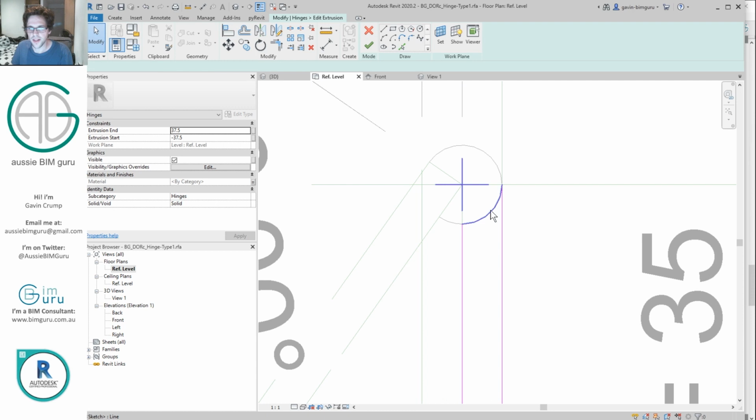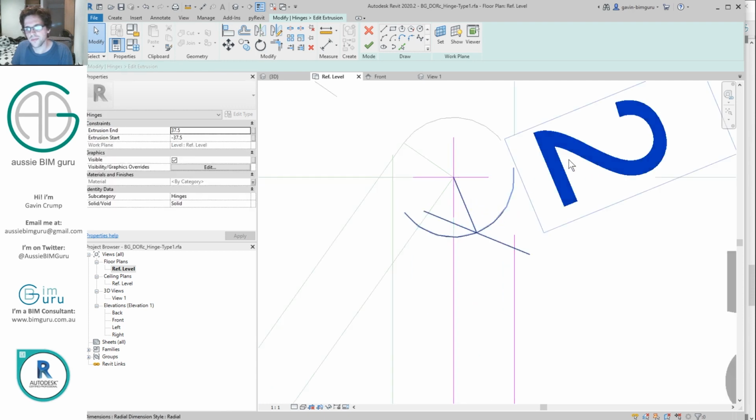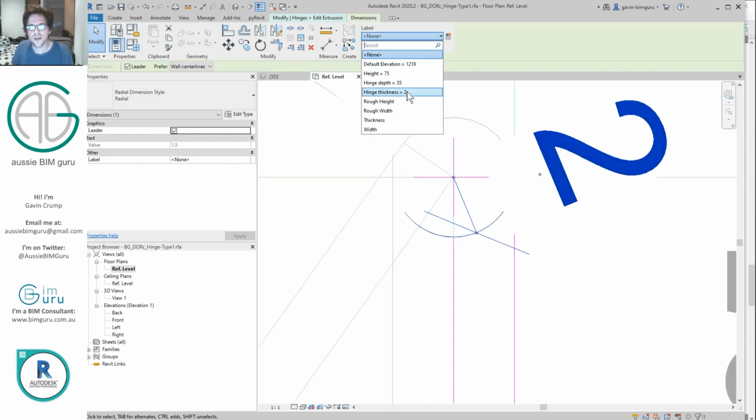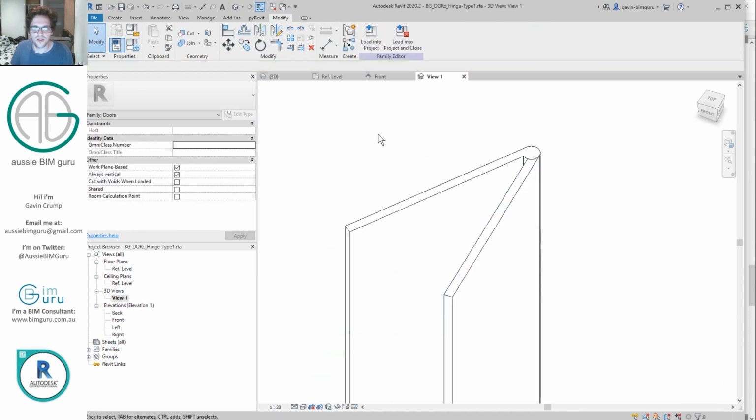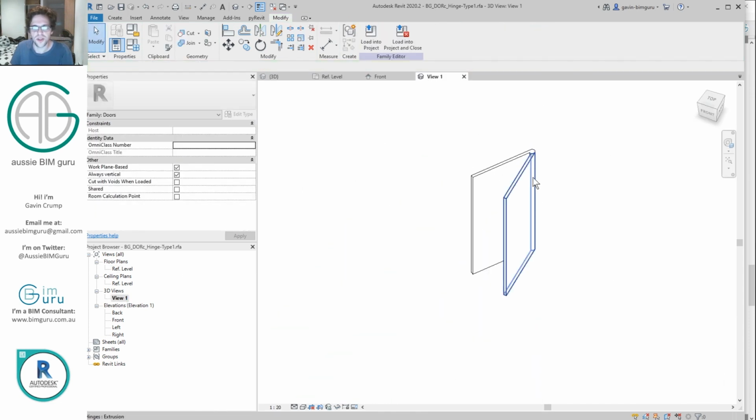And then just add that parametric radius as well. Make that the hinge thickness. That way it looks more like a two-piece hinge, so it looks a little bit smarter than joining the whole thing together. Now obviously this is a really oversimplified hinge. There's probably no hinge that quite looks like this in the real world.